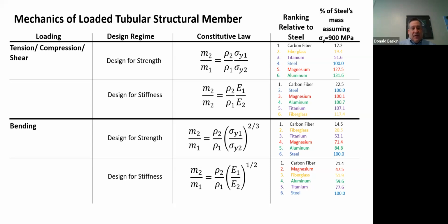People have tried using cut up little fibers and mixing them together in some random orientation and locking them in those directions with epoxy or polyester, whatever resin material. Those materials do approach isotropic behavior, but almost by definition, because they're getting to isotropic behavior, they no longer have the structural efficiency.